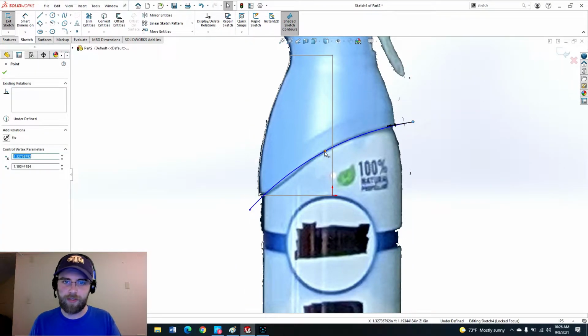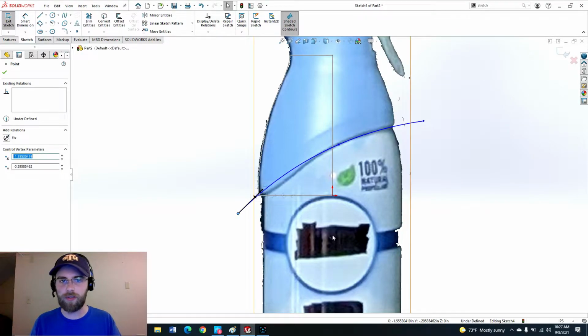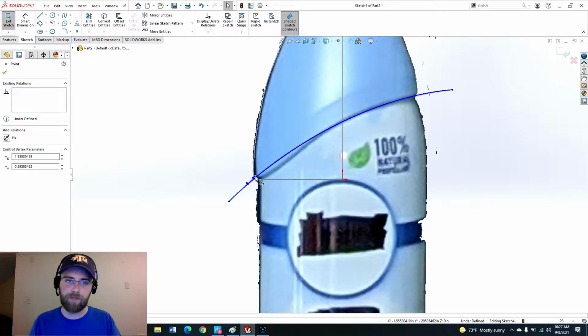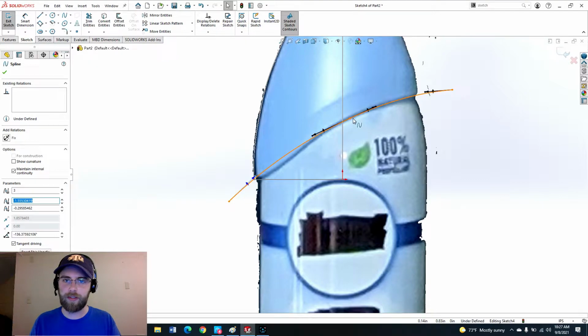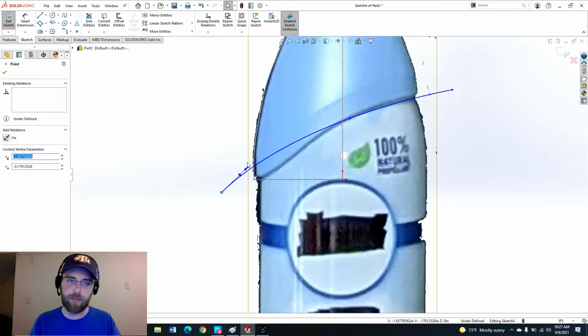And something I ran into when I was practicing this was some zero thickness geometry errors. And that's where I was trying to put the cut right on the edges of this revolve feature. So you'll notice I'm sort of drawing these lines outside the scope, because this is going to get cut away. But I'm drawing the lines outside the scope so we can't run into any geometry errors or things line up too closely. So we'll make sure everything is contained here. Bring this up, bring the spline handle down.